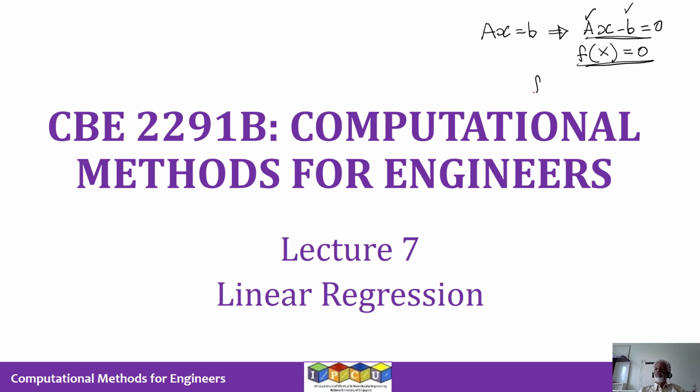We also looked at systems that can be described by this form, in general nonlinear: f(x, beta) = 0. We knew the function form, the nonlinear function form. We knew the values of beta, and then we tried to find the values of x. A particular example is the adiabatic CSTR problem, where, given the values of alpha, beta, gamma and the mass and energy balance equations at steady state, we were able to find the dimensionless quantities, in particular dimensionless concentration x and dimensionless temperature y.